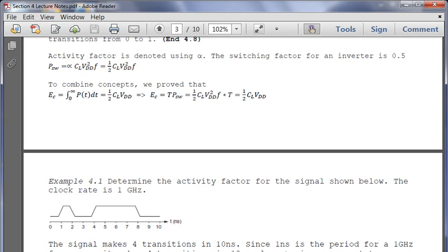We're actually going to be using AND gates and inverters and transistors with an enable signal to not allow power consumption past this point in the circuit. Therefore, this circuit will be off when it doesn't have any kind of activity. So we're going to be trying to turn portions of the circuit off while it's not being used.